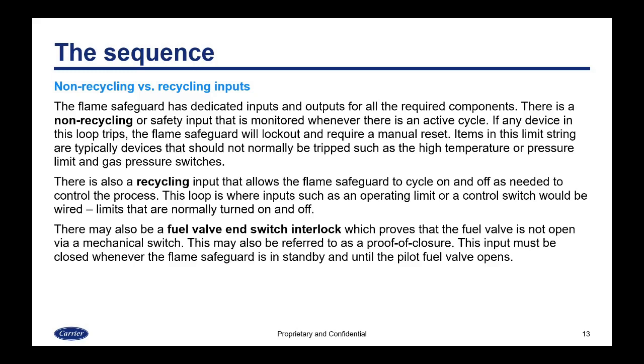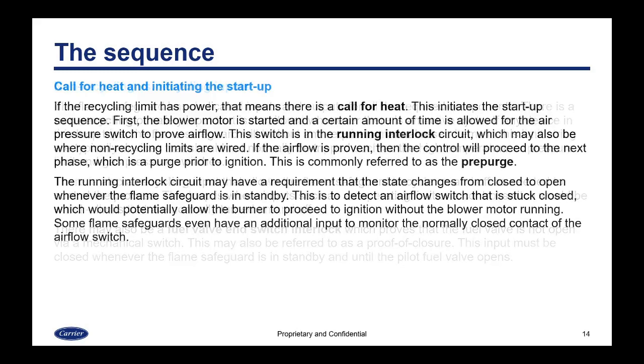There may also be a fuel valve end switch interlock, which proves that the fuel valve is not open via mechanical switch. And that also may be referred to as a proof of closure because it means that the main fuel valve is actually closed, no fuel is going through. This input must be closed whenever the flame safeguard is in standby and until the pilot valve opens.